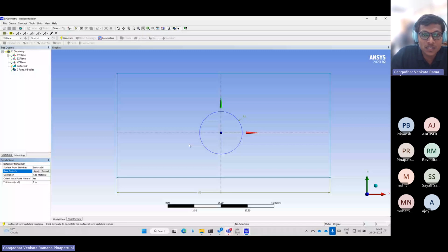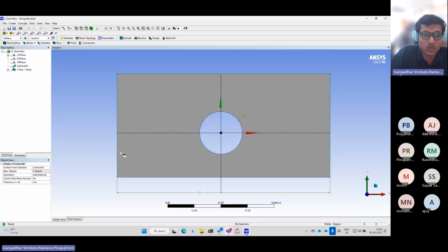So only in the selected region, my fluid comes from here. This is my boundary, inlet boundary. I say this is my inlet. Fluid comes in this boundary along the surface. You'll be taking this as a fluid domain, and it travels along the cylinder, around the cylinder, and the flow physics around the cylinder you will see very soon. Okay, in a similar way we are going to simulate these things. That's why we are creating a surface of a circular cylinder and a rectangular domain around this.